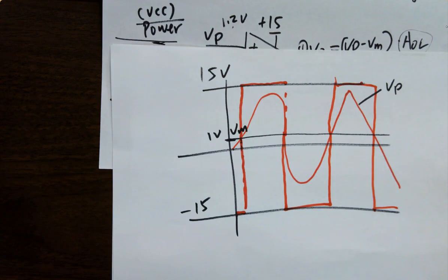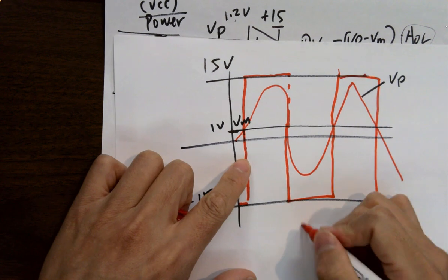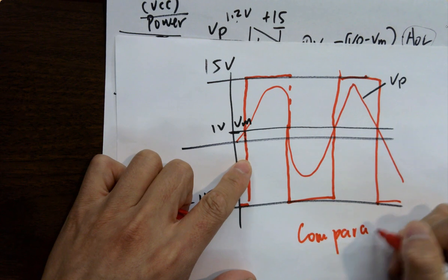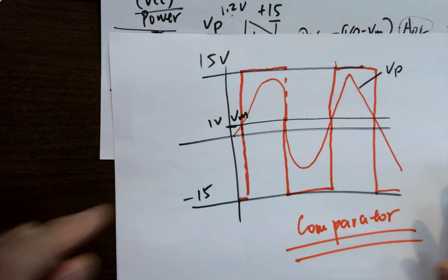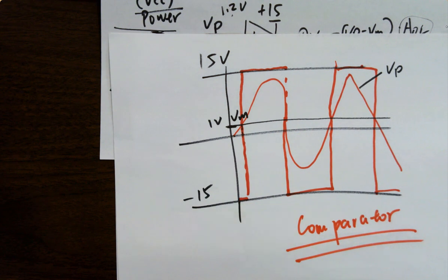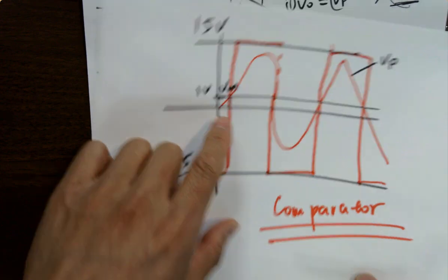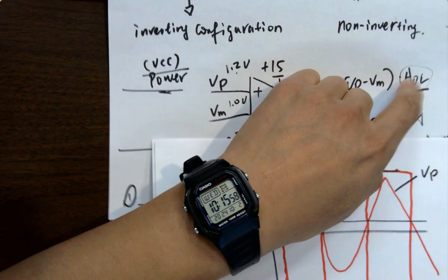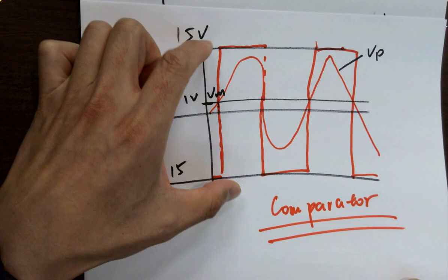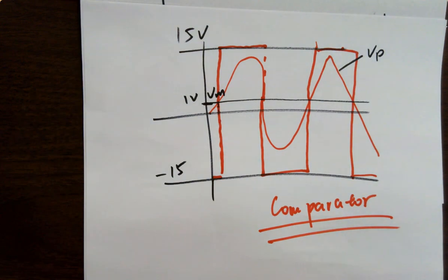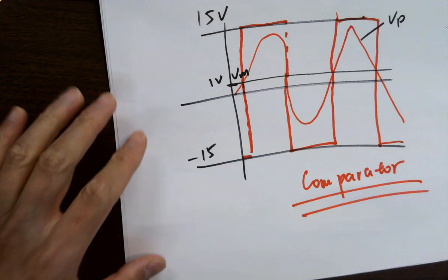What is this called? It's called a comparator. Super important in practical circuits. So if you keep this open loop, it's going to form a comparator. It's using that open loop gain to amplify the differences between the two signals. So is this basically just turning an analog signal into a digital signal? Yes. Okay. Yeah. So what's going on for the little robot car there?